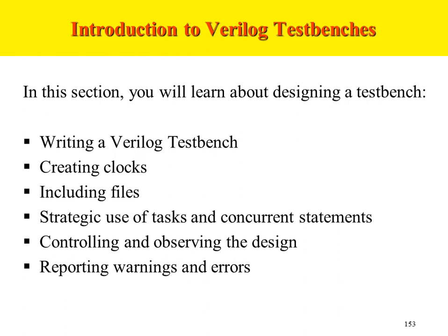A similar concept we are going to apply with a Verilog test bench, where the design that you have created is called the design under test, or DUT. We apply some inputs to the design, and based on the logic of the design and the current inputs, it will generate some outputs. We monitor the inputs and the outputs generated.